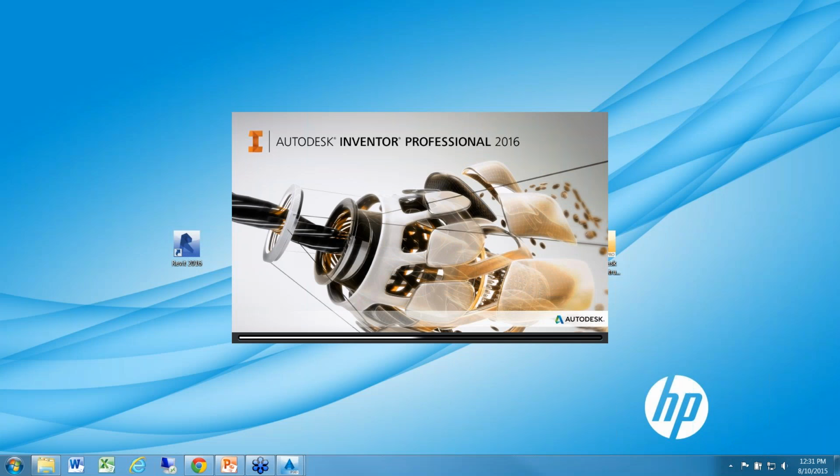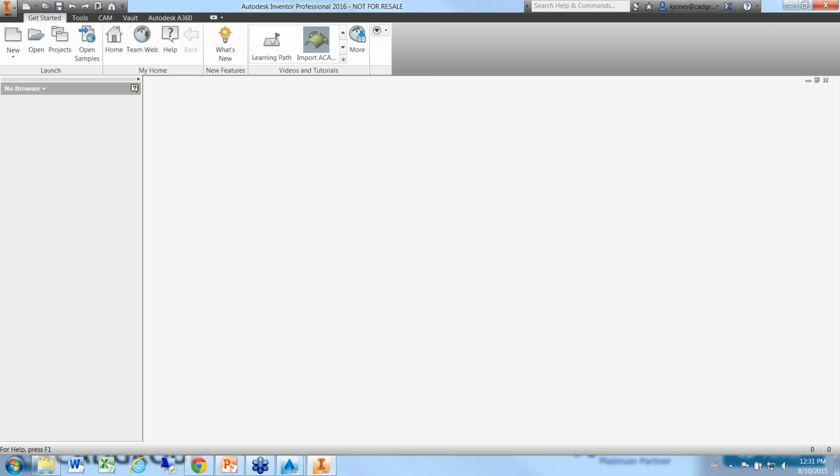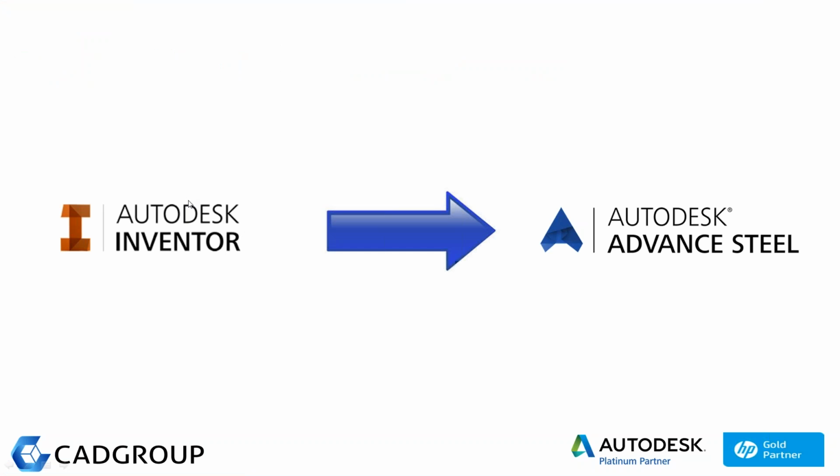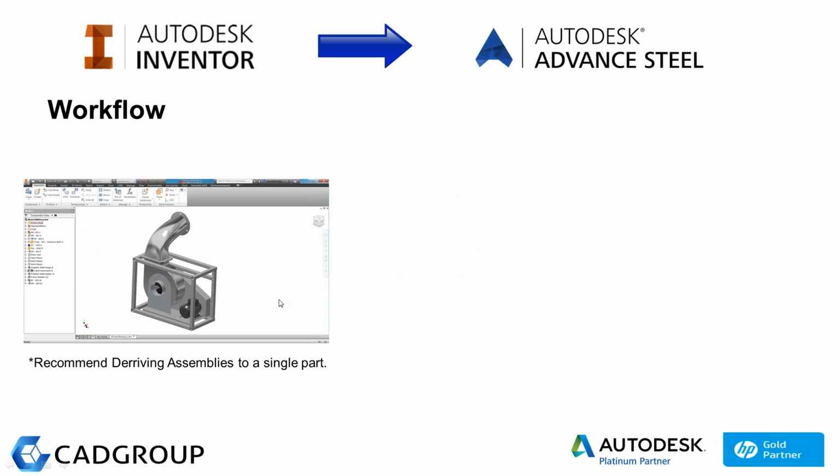So from this last stage with Inventor, guys, while it's up and running, I'll drop back into the PowerPoint for a moment. Again, looking at the process to get us from our plant and equipment. Ideally, what we can do is look at bringing Inventor data. Quite typically, Inventor models are made of lots of components. So if you're going to bring a piece of equipment across to Advance Steel, first derive that inside Inventor.